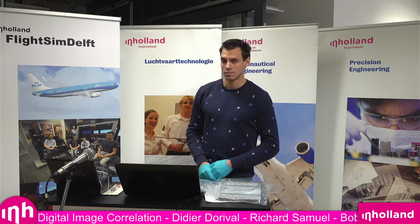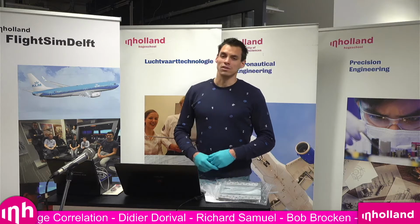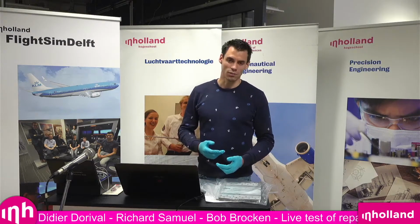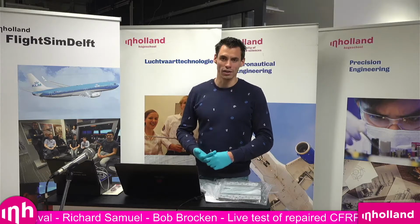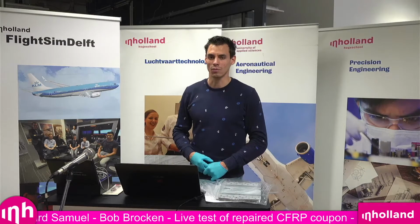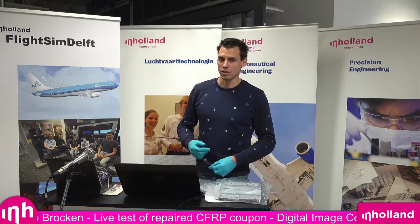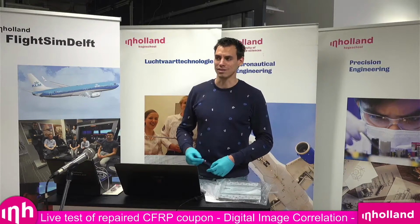Someone is asking, damage due to drilling possible? Yes, in this case it is, but if the alu plate transfers the load to the composite plate through the glue layer, it shouldn't break at the area where it did. So it could be due to some bending, due to the clamping, and this is also very typical for testing, that it's quite difficult to test something properly.